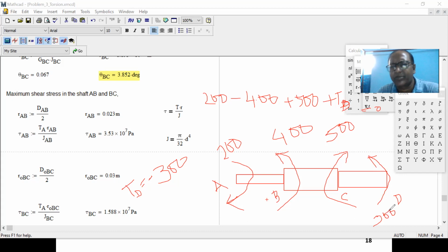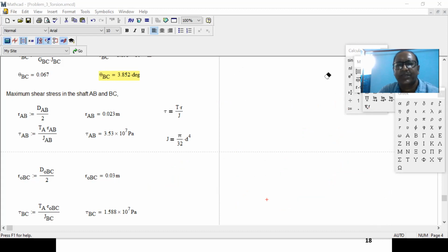But you need to figure out, okay? Now, you see balance, you sum all anti-clockwise. This is anti-clockwise, this is anti-clockwise, so 700. And clockwise, this 200, this 500, 700. That means balance. Now, if I say figure out the torque in each section, then how can we do it?